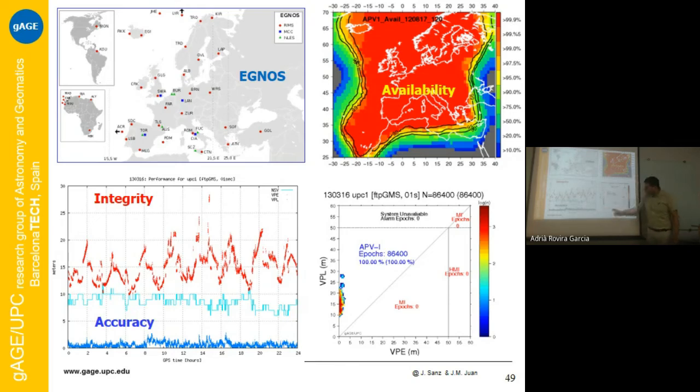Actually, we can see it also with these so-called Stanford plots when we are plotting the protection level, this red protection level against the blue, against the actual error. We again see values that are on this side of the diagonal. Small errors, bounded with high, adequate protection levels.